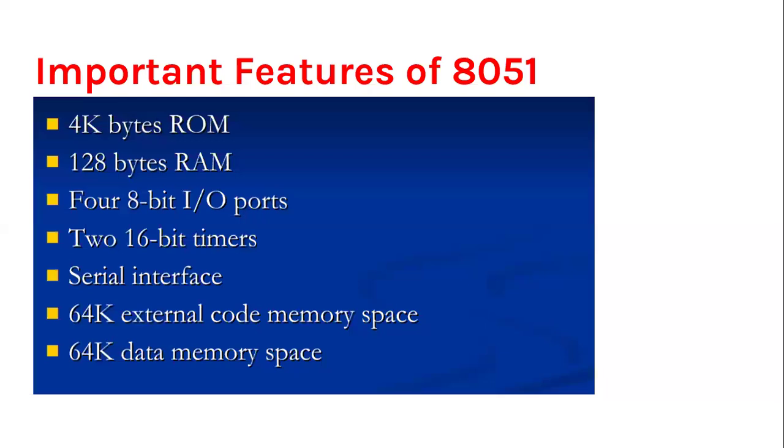The 8051 features are 4 KB ROM, 128 bytes of RAM, and 4 IO ports, each port having 8 pins. Remember this, guys, because we must use only this in the entire workshop. We are using these IO ports. So clear, guys?